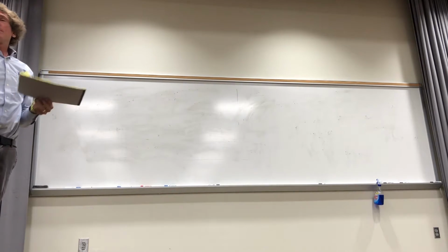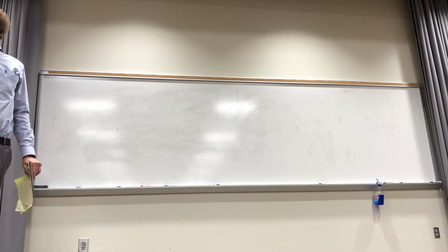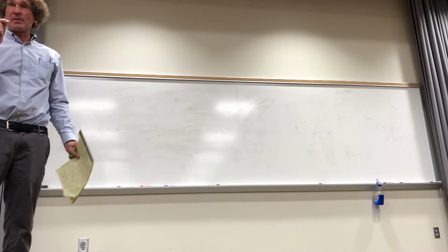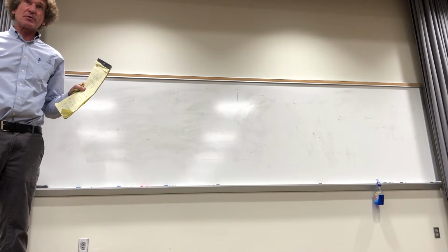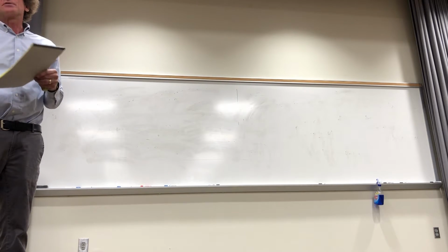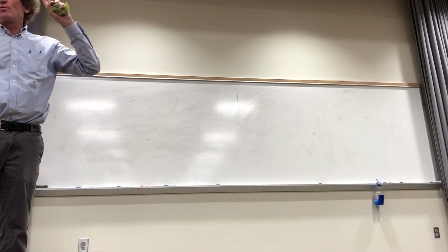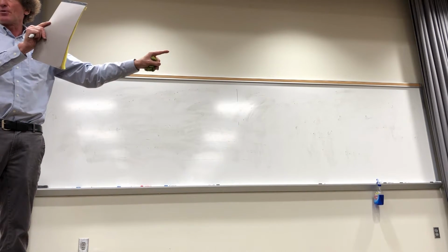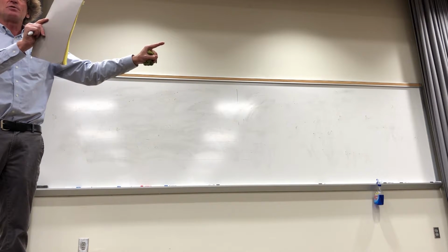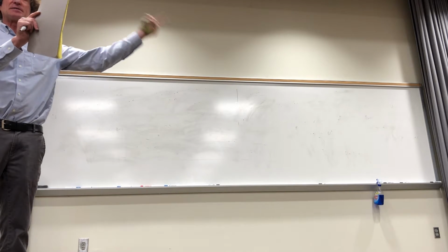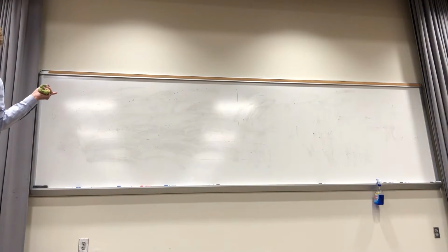What he's saying is this. I have an input-output for only one filter, right? The output of my filter feeds the next filter, and then the output of that filter feeds the next filter. So I have three separate difference equations. His book has one big monster difference equation, where he takes H1 in Z, H2 in Z, and H3 in Z and multiplies them. And so he gets terms that have Z to the 6th, which means he's going to have to take N minus 6 type terms. At least I don't want that because, frankly, it's just too messy. But you can do it that way.